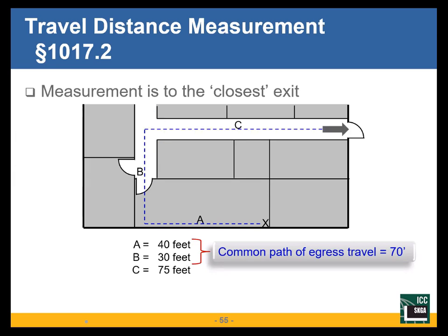I continue to measure, and then I add them together. Travel distance of 145 feet. Oh, good. I had 200 feet to work with. It complies. But it's not always the furthest room that has the longest travel distance.